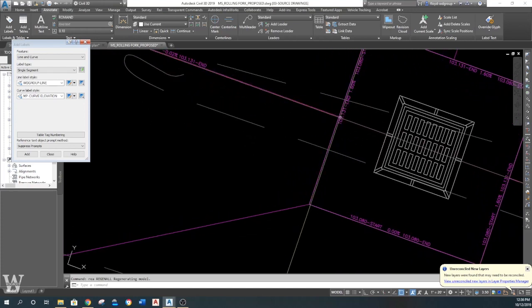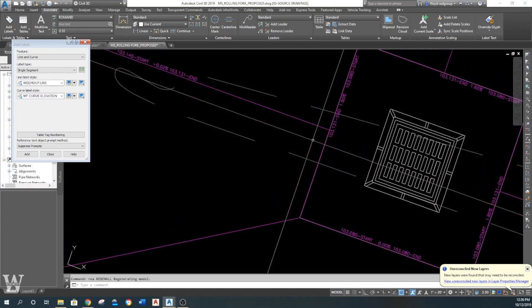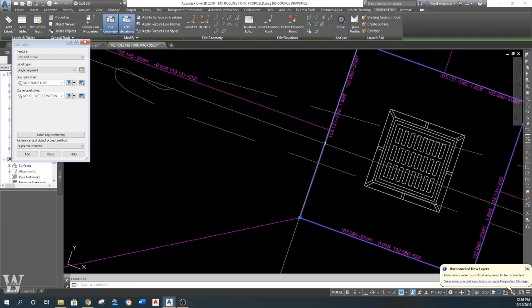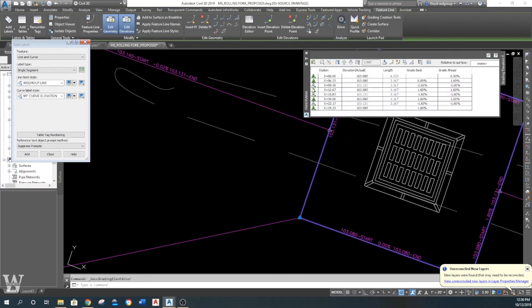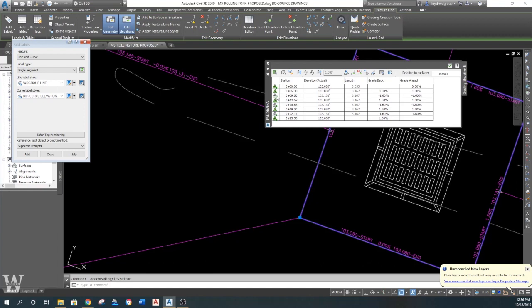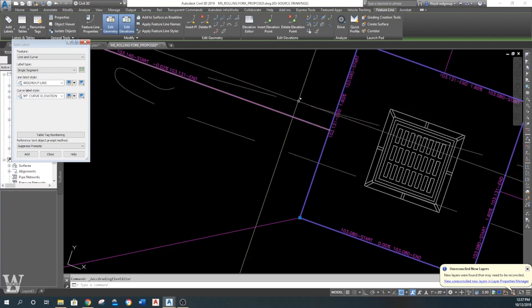It actually picked up this elevation. So what we need to do, I think that's what I was telling you earlier, and it didn't pop up, but your elevation marker came up, and these white marks are every time these feature lines that don't have points in them try to cross, and it's picking up the elevation from the line that's crossing it.